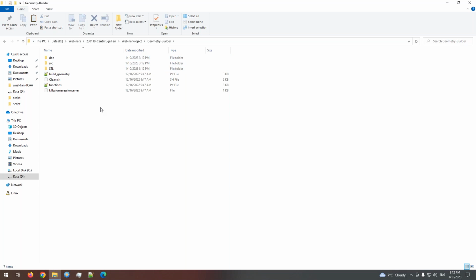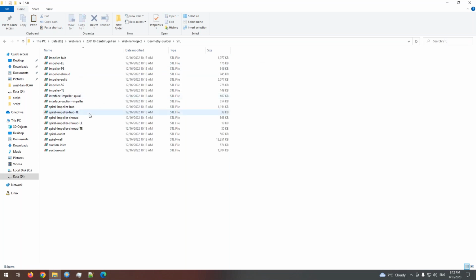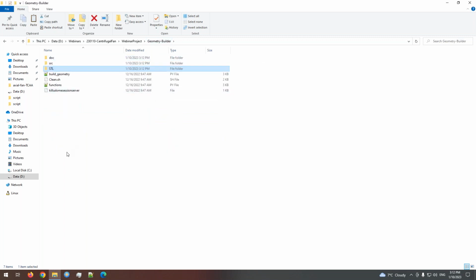So what I need as the first step, I definitely need the inputs. Usually for CFD simulation, it is a geometry which is the most important input. So I will be using this STL to set up the mesh for the computation. Then I will set the CFD simulation. Then I will put everything into the optimization loop.